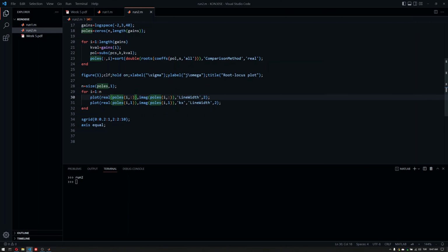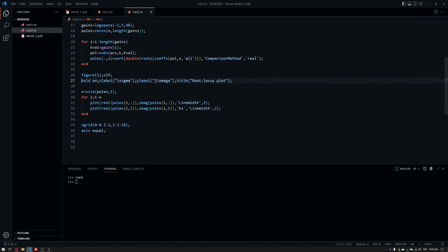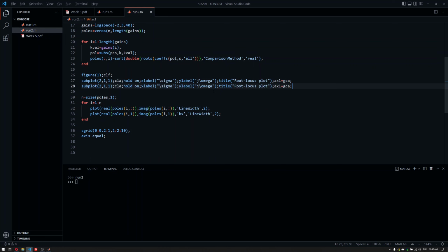So I'm going to just create a subplot at this point. Let's have 2 rows, 1 column, and the first one of that is going to be this here. Let's call it AX1. Let's create another subplot. This time around it's going to be time, it's going to be YT, and we'll call it step response.